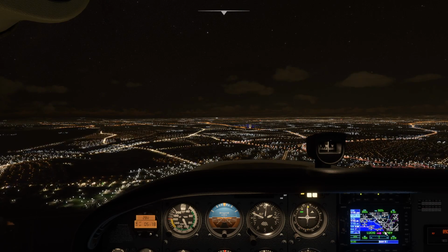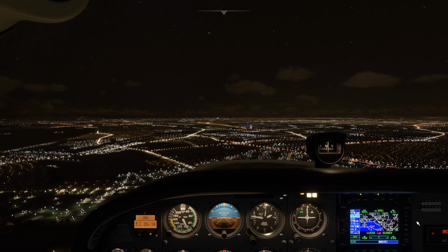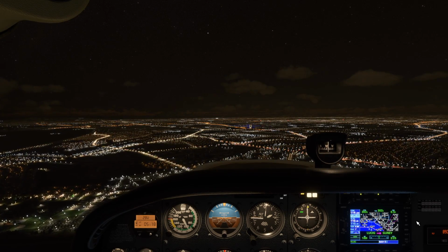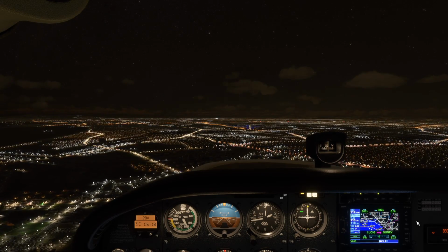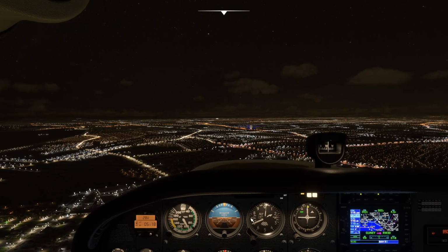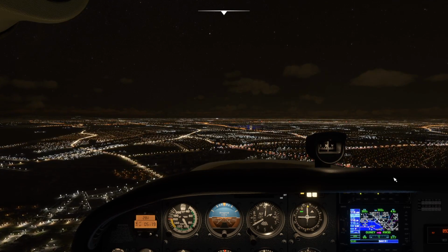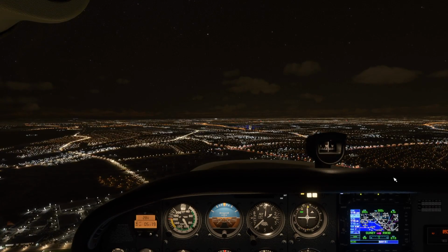So you may notice that we're actually not at the Gunny waypoint yet, so that means we captured the glide slope a little early. But if we didn't, we just basically need to make sure that when we get to Gunny, that we are on the glide slope, and we already are, so we're in good shape. You can see that our altitude's being handled by the autopilot, and I'm just lowering our throttle and making sure that we're going.